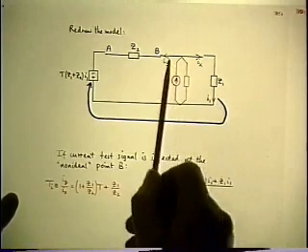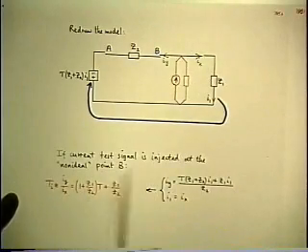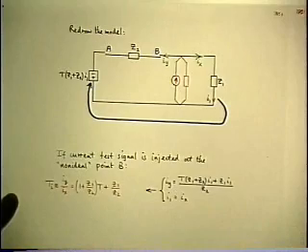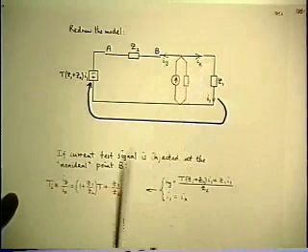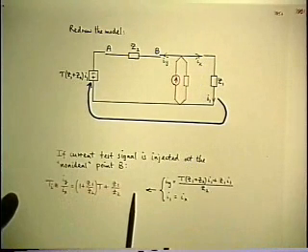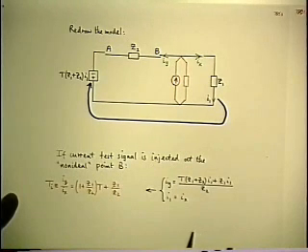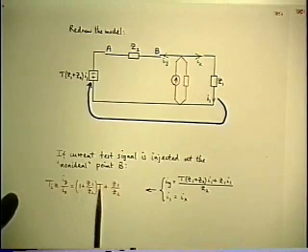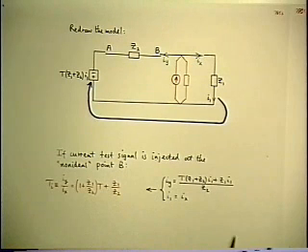Okay. We're going to measure Iy over Ix, call it a ratio T sub I, and the question is, is it equal to T? And when you go through the same little derivation and solve for Iy over Ix, unlucky again. It isn't T. But it tells you what the ratio of the impedances has to be in order to get close enough to T, and you see it's a dual result. Not surprising. And the only difference is it's the ratio upside down that matters this time.